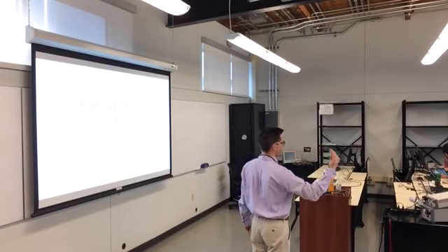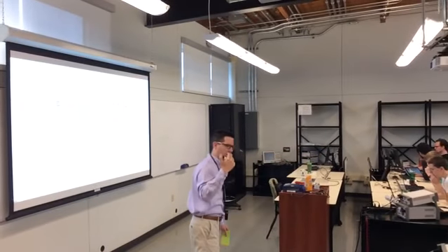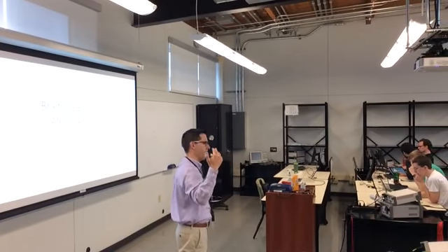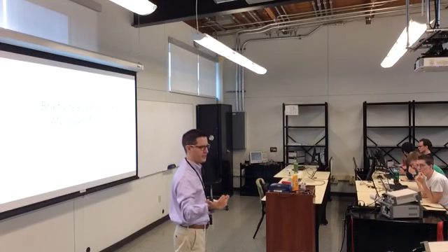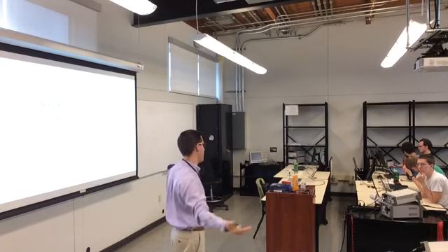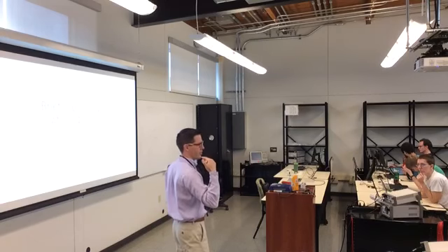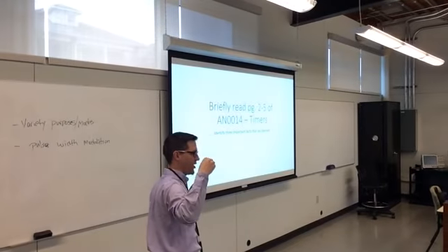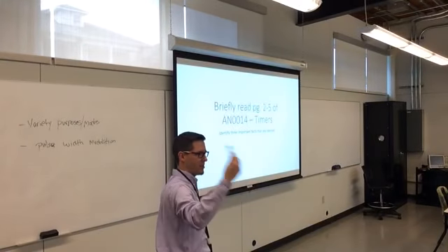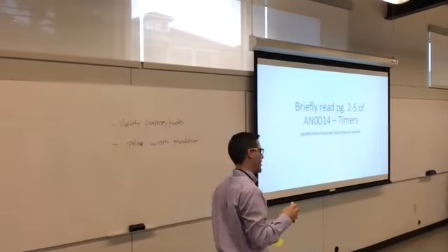At the same time, there are a lot of sensors that will generate a PWM signal that indicates some sort of process. Maybe you're measuring RPMs, maybe you're measuring speed. That comes out as a PWM signal. You don't want to write code that is constantly going, did my bit change, did my bit change? You would rather have the timer do that on its own.